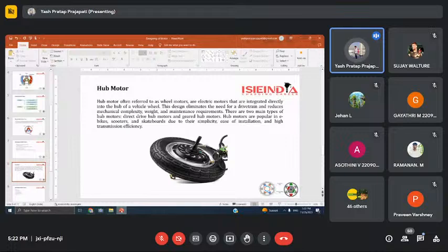And how does the circuit know which of the 9 coils to switch on and off? The Hall effect sensors positioned between some of the coils sense the permanent magnets on the outer rotor as they sweep past them. The Hall effect sensors figure out where the north and south magnetic poles of the rotor are, and which coils to activate to keep it spinning.